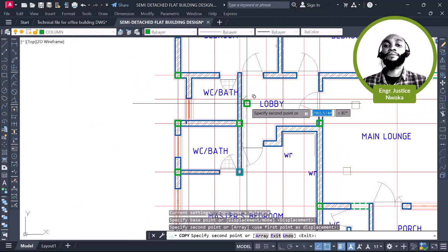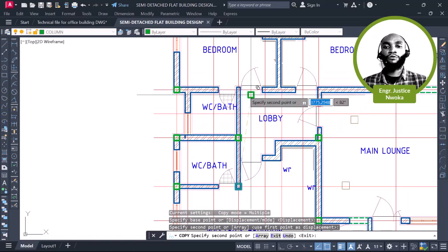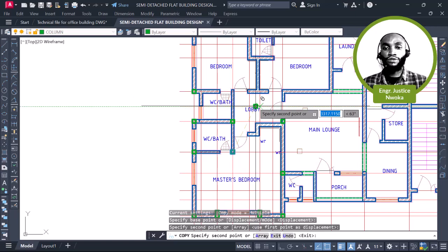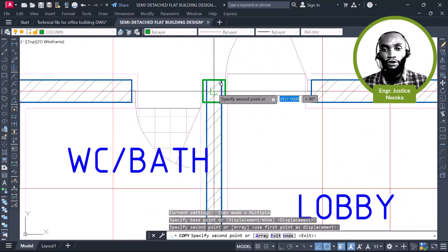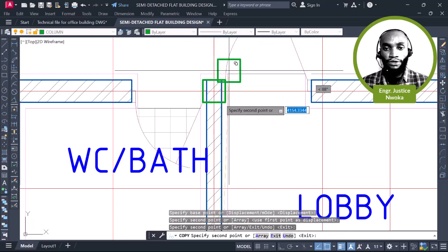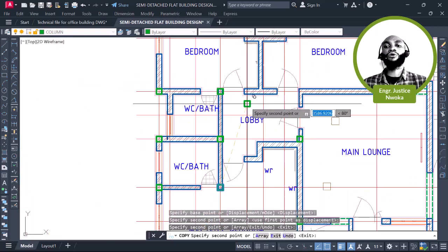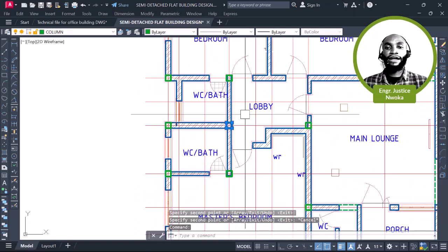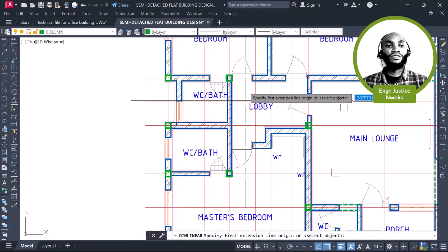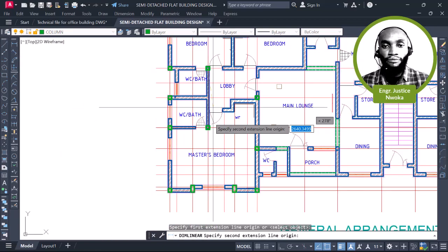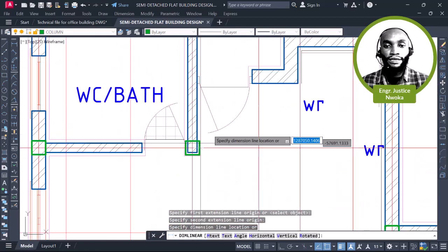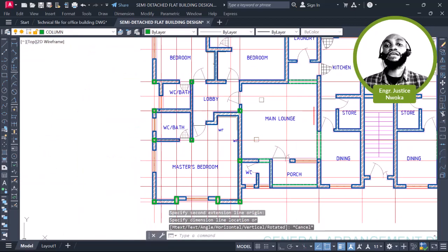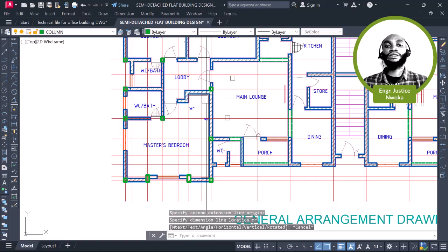Then we go again. I don't want to place anything around this place here. But I can still come here and place my column here. They should use a 9 inches block wall here. That will be okay. So with that, I can choose to remove this column here, because from here to here we have almost 4 meters. That's fine. So I want this arrangement here.